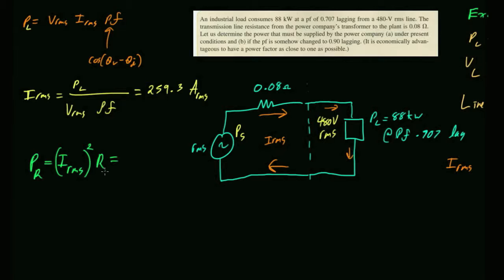So this is really interesting, right? The power company basically has to supply 88 kilowatts at the source plus the 5 and change. So what is that, 93.4 kilowatts? Okay, so what happened to that 5 kilowatts? Gone! That's a lot of power, right? 5 kilowatts to keep the lights on for a little while. Yes, sir? That's the power across the resistor, the second one? Right, that's the power that's lost across the resistor. That's just being dissipated as heat in the line.